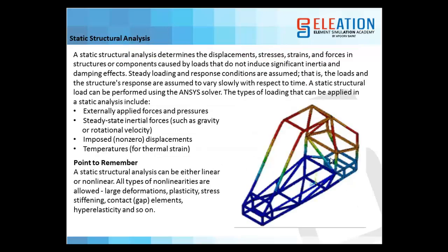Static analysis. So what does static analysis actually mean? Static structural analysis determines the displacement, stresses, strains and forces in a structure or a component caused by loads that do not include significant inertia and damping effects. Steady state loading or response conditions are assumed. That is, the loads and the structure's response are assumed to vary slowly with respect to time.